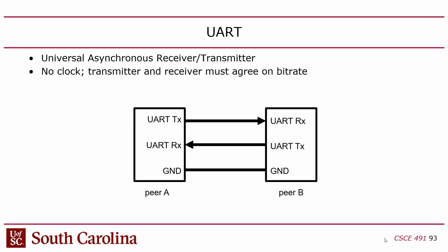None of them support uncoupling until you go to a differential, like PCI Express and HDMI and DisplayPort and SATA. They use a differential system, so each bit is sent on two wires that reverse voltage relative to one another. Also, CAN, the controller area network that cars use, that's how your auto parking stuff works, like in your self-driving. That's also a decoupled bus, I believe. I don't think you need a common ground for that one either, because the way that one works is it sends a 0 by shorting two wires and it sends a 1 by separating two wires. So it's uncoupled.